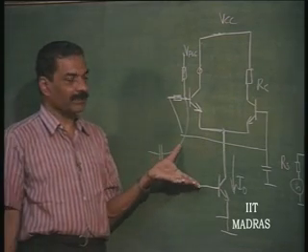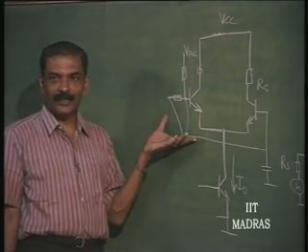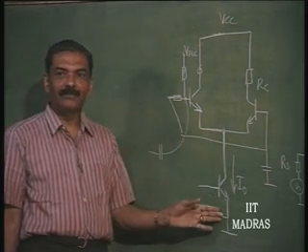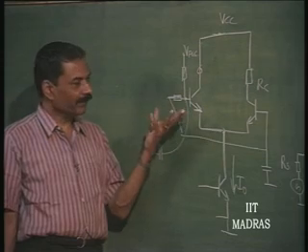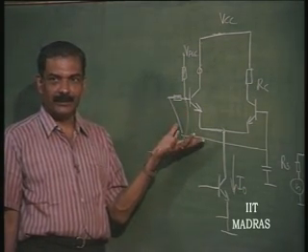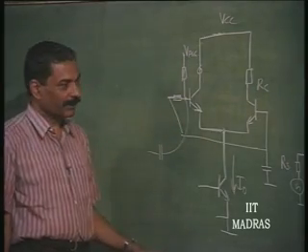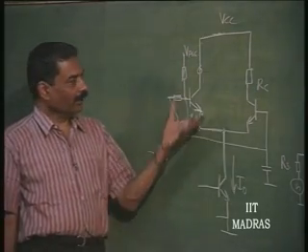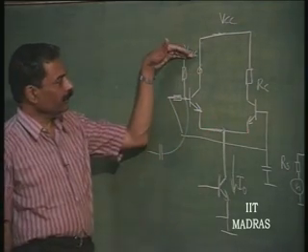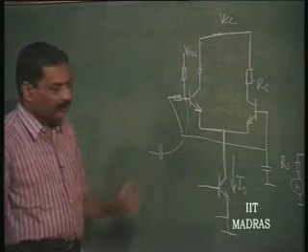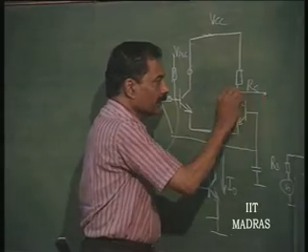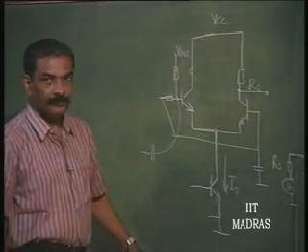But this does not have that disadvantage of AGC etc. and y parameters not varying etc. Y parameters will vary as I naught varies, okay. And that therefore, if it is a fixed frequency, okay, amplifier without a requirement of AGC, okay, this stage can be used, wideband structure for tuned amplifiers, or it can be straight away used for video amplifier where you do not apply the AGC. This AGC terminal is not used, okay. So, you do not connect anything there. So, this is one way of using this as a video amplifier, okay.